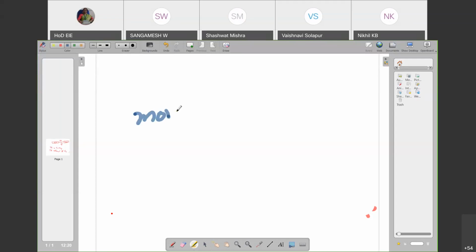You have to shift it because in order to get this, you have to move it ahead of G1. And again, you have to remember that when you are moving the summing element ahead of G1, it is having an attachment of H2, right? So that attachment has to be taken care of.